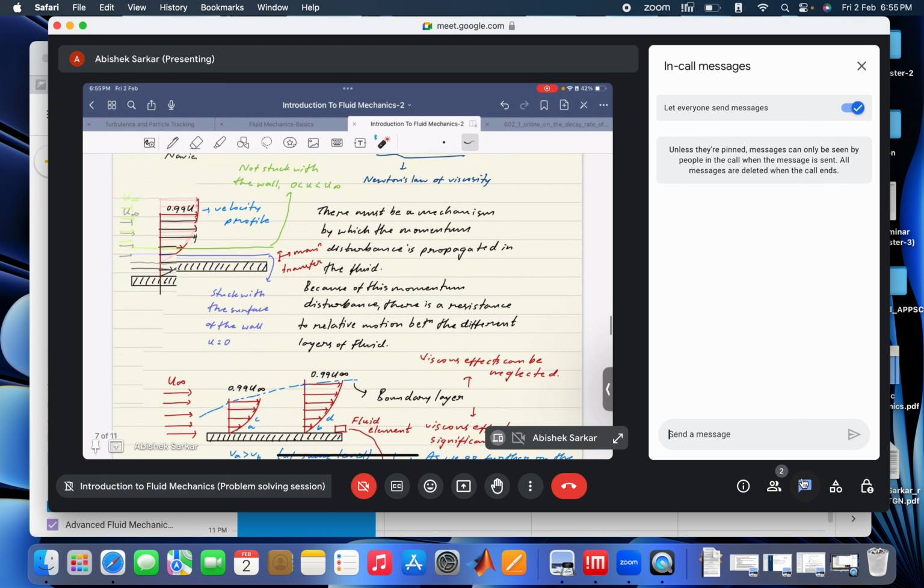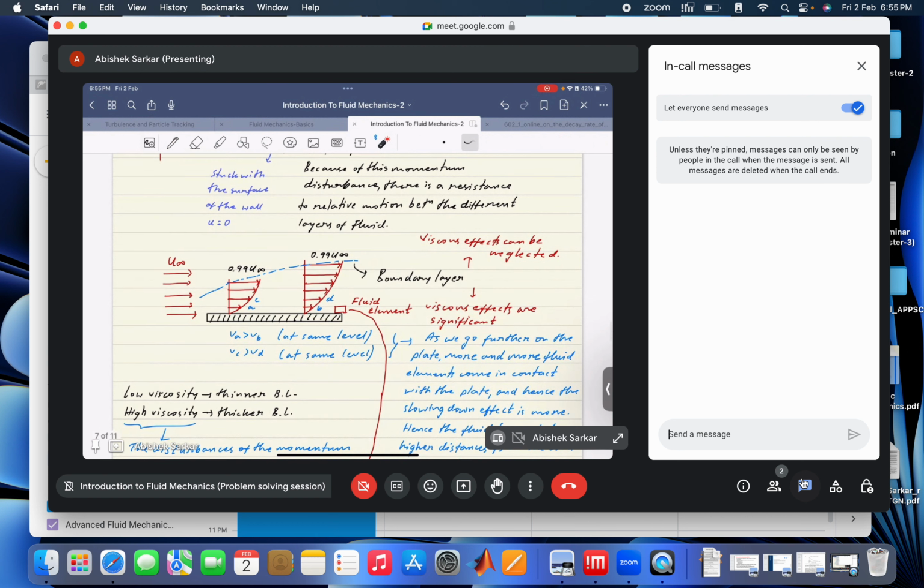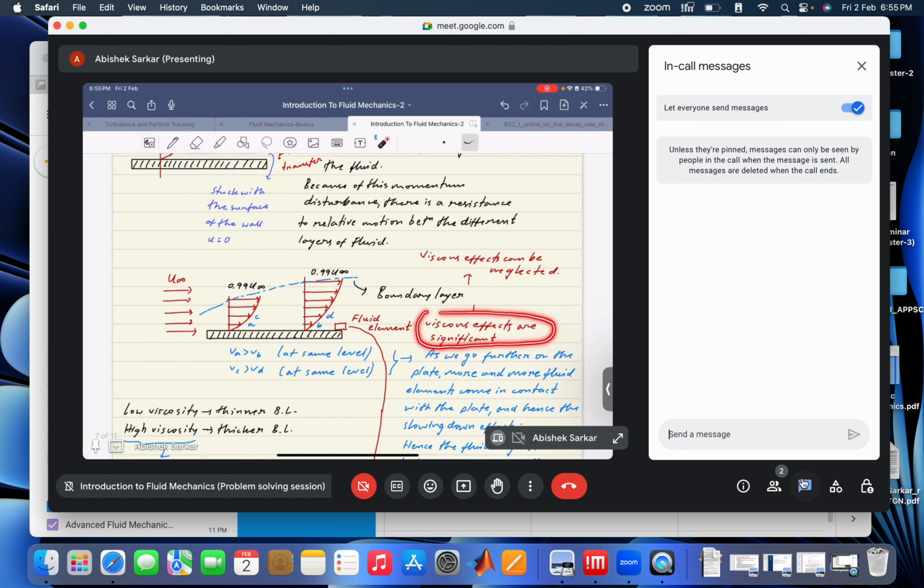So if you consider this as a boundary layer, the very concept of the boundary layer is to differentiate two distinct layers of the fluid flow, where one layer majorly comprises the viscous nature of the fluid flow, which is within the boundary layer. The viscous effects are significant within the boundary layer, and the inviscid region or potential flow region is where the viscous effects of the fluid are almost zero, and that part of the fluid flow can be solved or considered via potential flow theory.